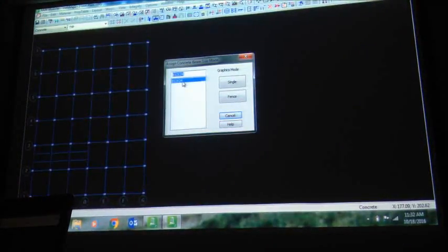I can again assign the beam sizes. Again, if you click on that, you can, where is the assignment? Assign beam size, you can do that, or you can go layout, beams, assign beam size. Remember, we already generated one beam size, and if we say fence for all of them, it's already designed. Now if you want to know whether it's designed or you assigned it, click on this button, which will show all the numbers.